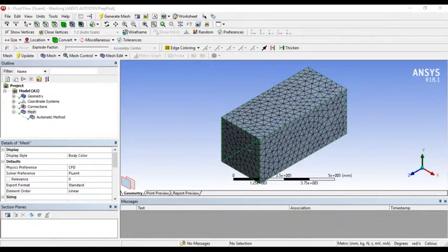our mesh is generated here. You'll see this is a non-structural or non-uniform mesh. With this type of mesh, you'll get some distorted results. But you can do this analysis on this type of mesh only, but make sure that in the analysis you step up your iterations up to 100 or 500. But I'm creating a uniform mesh here.